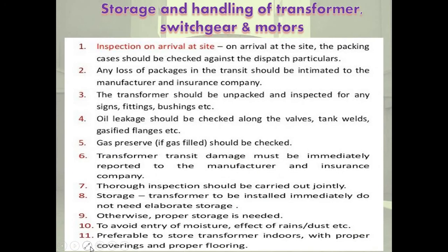Okay, now storage and handling of transformers, switchgears and motors. The machines should be stored in a clean, dry storehouse having uniform temperatures. Firstly, the inspections on arrival at site. On arrival at site, the packing case should be checked against the dispatch particulars. Any loss of package in transit should be intimated to the manufacturer and insurance company.